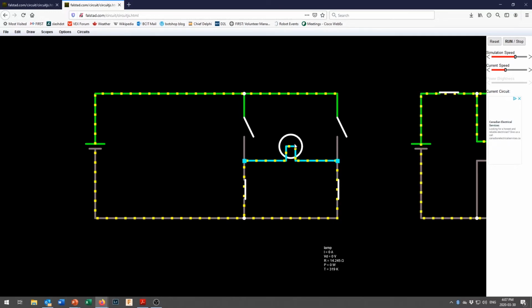In fact, what you'll actually get is a motor braking effect, where if the motor's still spinning, the electricity that the motor generates will form a little loop right in here and come back and push on itself and cause its own self to slow down. So if you've seen cordless drills or cordless power tools that have braking, that's how they're doing it. They're messing around with the H-bridge and giving it some interesting directions to go.